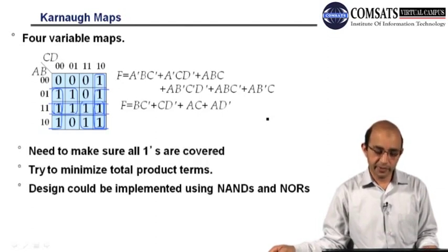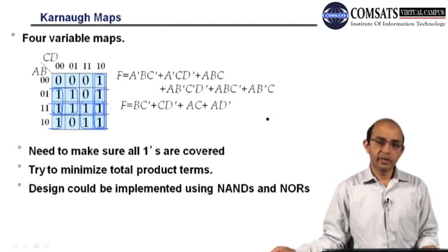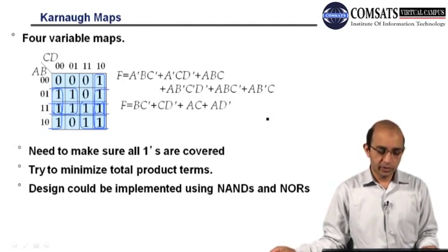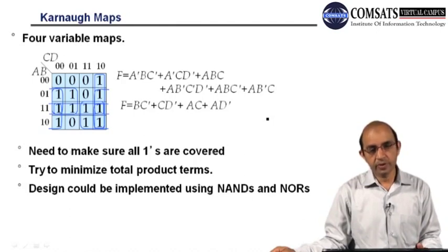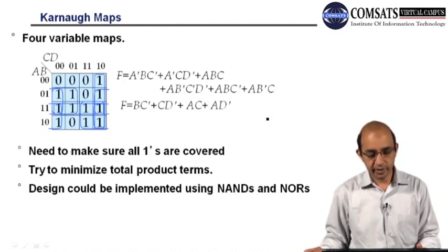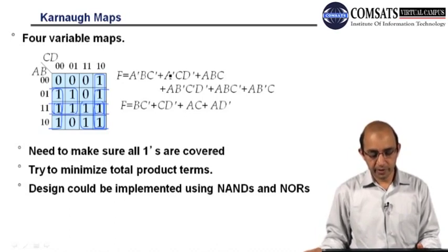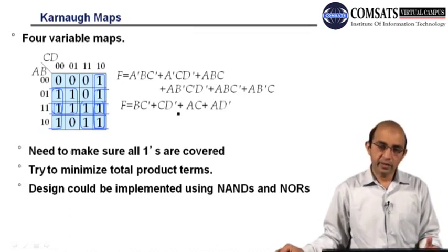There are some tips which we normally should follow. We have to make sure that all ones are being used properly. And for more simplification, we must minimize the total product terms. Here if you look at this expression, we have more product terms, but over here we have fewer product terms.